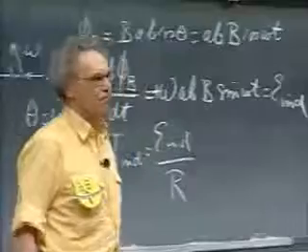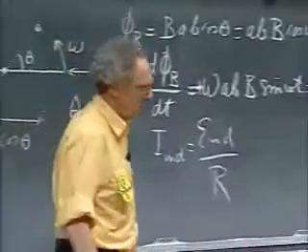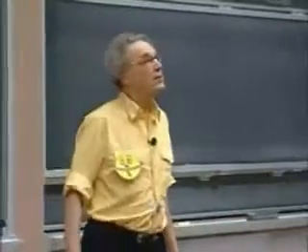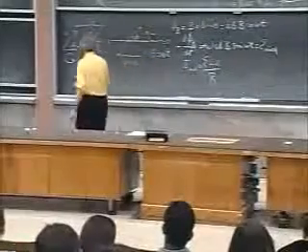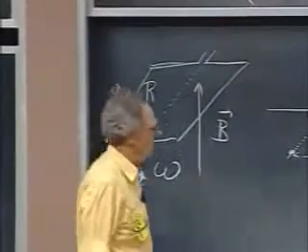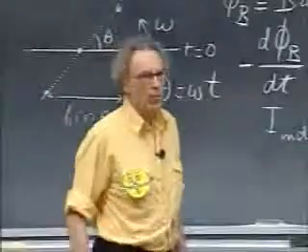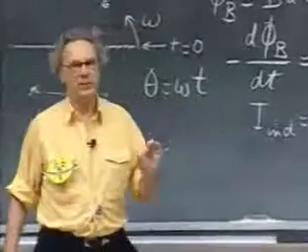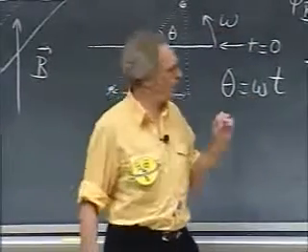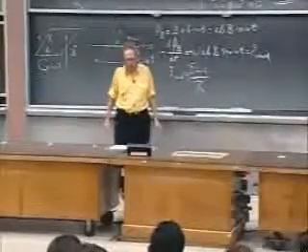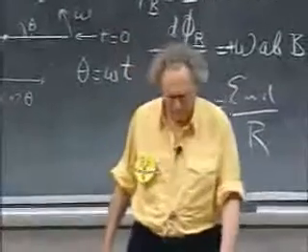You built motors, and during the prize ceremony, I told you that the faster your motor rotates, the larger the induced EMF is, which is generated in the loop. You had a magnetic field, which let's assume is more or less constant. Of course, it wasn't in your case, but let's assume so for the sake of argument. And as your motor rotates, there was an induced current generated by Mr. Faraday, which is proportional to omega. So the current is larger when your motor goes faster. And that induced current opposes the current which was produced by your battery.